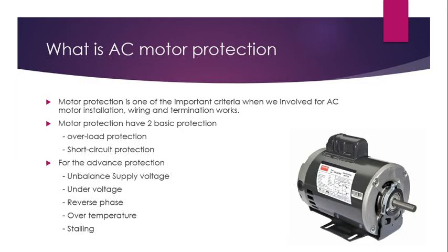Okay, what is AC motor protection? Motor protection is one of the important criteria when we involve the AC motor installation, wiring and termination work. Second, motor protection has two basic protections. First, overload protection. Second, short circuit protection. For the F1 protection: unbalanced supply voltage, under voltage, reverse phase, over temperature, stalling.